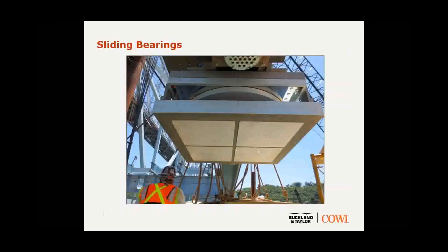Showed you this picture before. The bearings themselves had an extra element added to the bottom, which was the erection sliding element, and that's these Teflon panels. We had grease tubes inserted in this bottom plate as well to help maintain grease levels as the slide went on.